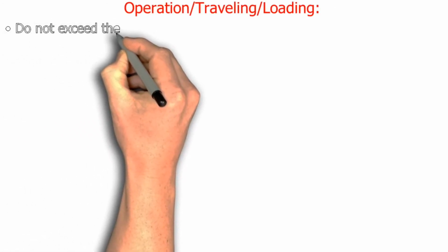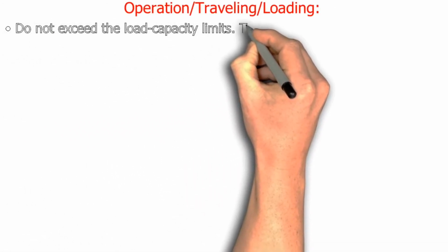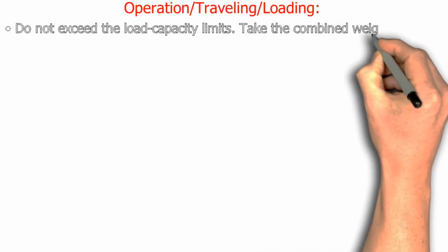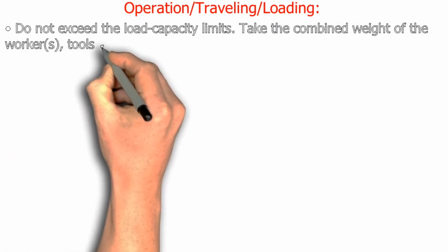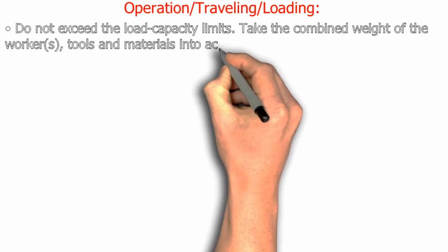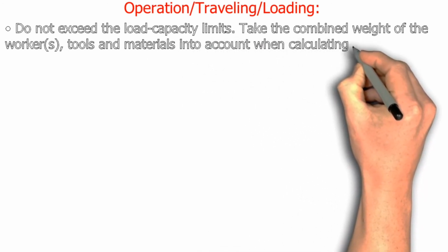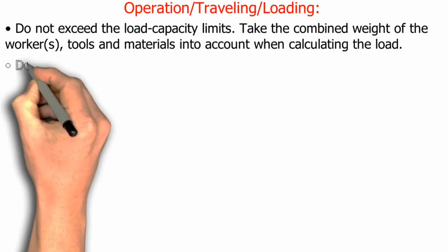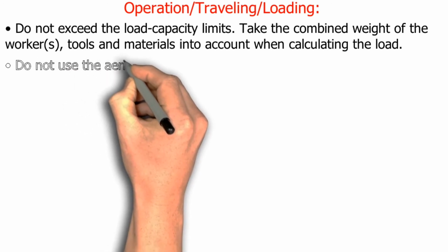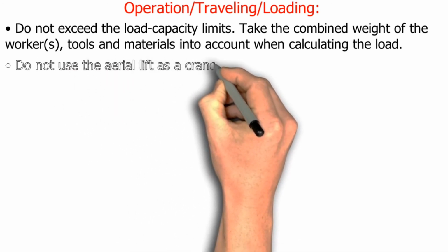Operation, traveling, loading. Do not exceed the load capacity limits. Take the combined weight of the workers, tools and materials into account when calculating the load. Do not use the aerial lift as a crane.